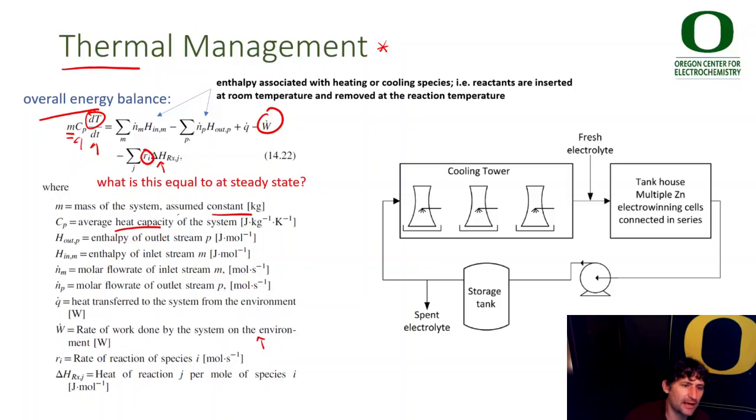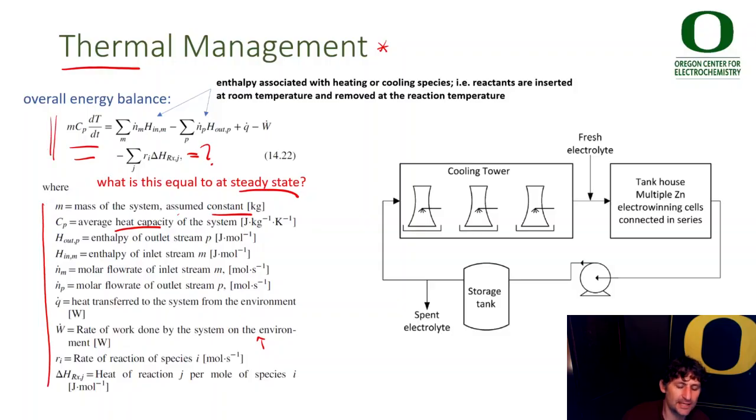One thing you might think about is what this equation is equal to at steady state. So what does this equation equal at steady state? We won't talk a lot more about thermal management, but it's important to understand how you might need to engineer that to keep the temperature at the target temperature for a given reaction. You'll need to understand how much heat is generated and how the heat flows work in your system.